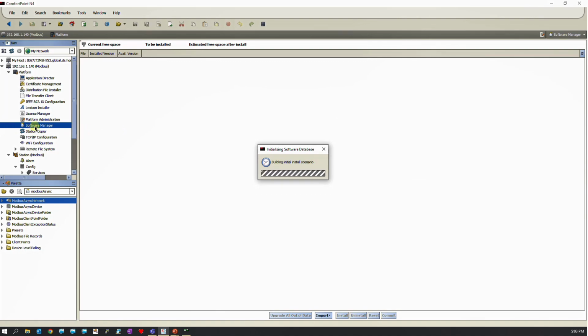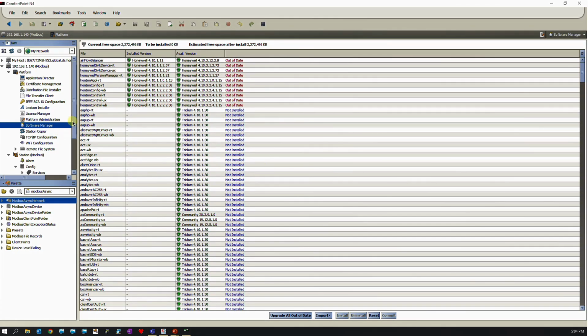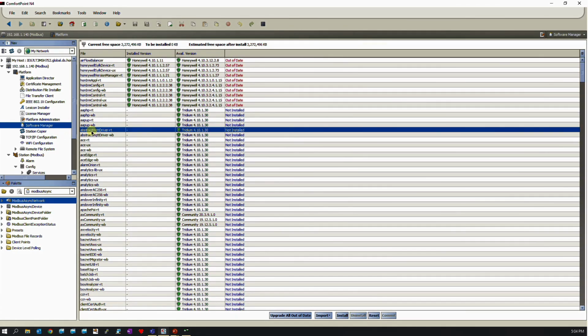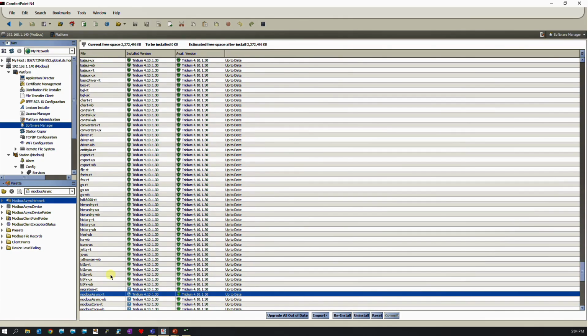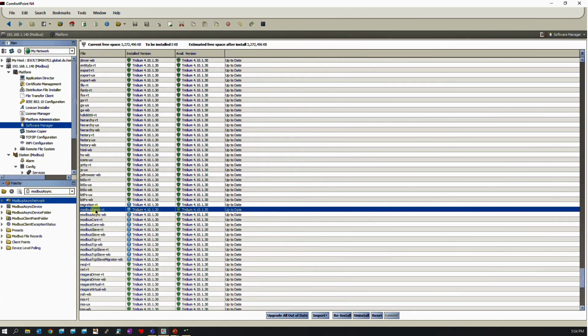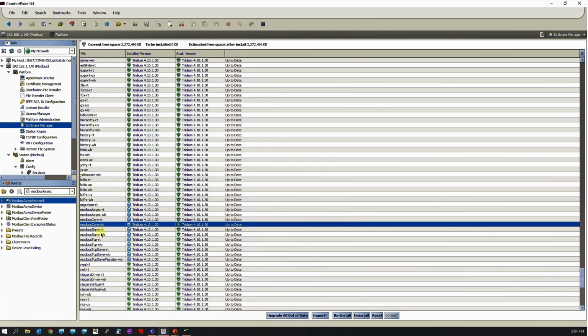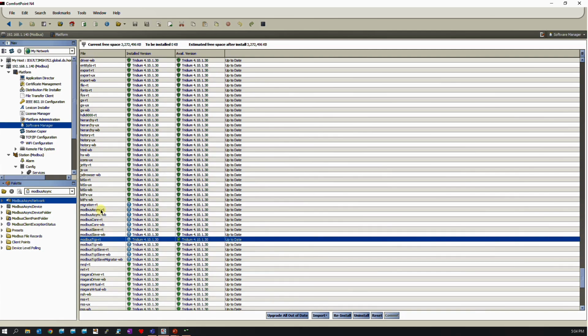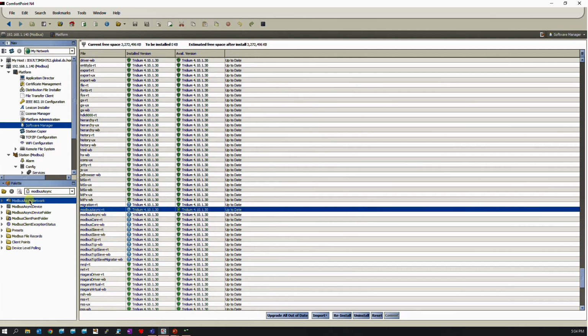If you go to your software manager here, this should list you all the Modbus async, core, slave, and TCP. All of this should be installed, or whichever you're working with, async network right now. This should be installed before you can add the network there.